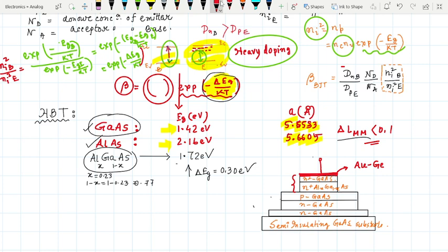So since it is inside, not aluminium, gold germanium alloy is taken as the metal contact to make the ohmic contact, because for n-type the work function of the metal species is greater than the work function of the n-type gallium arsenide. Now this is the emitter.